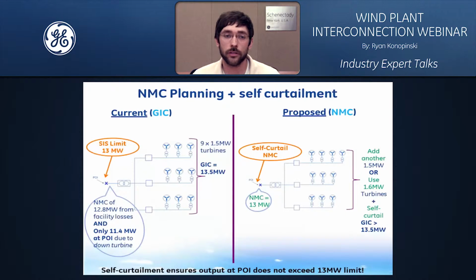So in this case, after electrical losses and environmental losses within the network, the net injection from this facility under perfect conditions, or essentially under full rated conditions, and under the assumption that all the units are online, is less than the reliability limit. Therefore, the facility would not pose any violation to the system impact study.